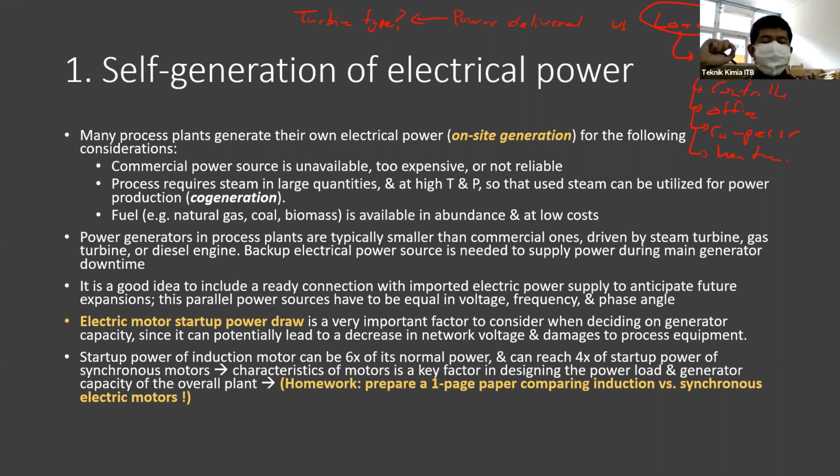It's very non-responsive, because you always have a furnace first, from furnace goes to boiler, from boiler goes to turbine, and then from turbine it will go to your electric generator. First step. It's difficult to control, but it provides higher flexibility of fuel.